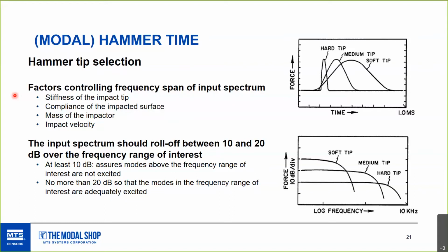Yeah, so with the different hammer tips, like I was just saying, the softer the hammer tip, you really customize exactly what that high frequency is you're essentially attempting to reach with it. That is ultimately controlled by both the mass and the hammer tip when it's all said and done. You can think of it like a car crash in a sense. With that softer hammer tip and more mass, you're squishing that tip more, so you're lengthening out the time of the impact, so that energy is really focused at that lower frequency versus extending up to a higher frequency with a hard hammer tip.